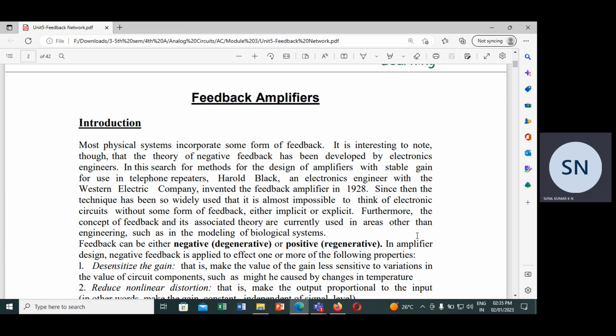We are going to see this when we characterize an amplifier. We expect that the input resistance should be very high and the output resistance should be very low, the gain should be very high, and the bandwidth should be very large. We characterize the amplifier by the input and output impedance as well as the gain, bandwidth and frequency response. In that same case, I am going to employ feedback, which we have learned.